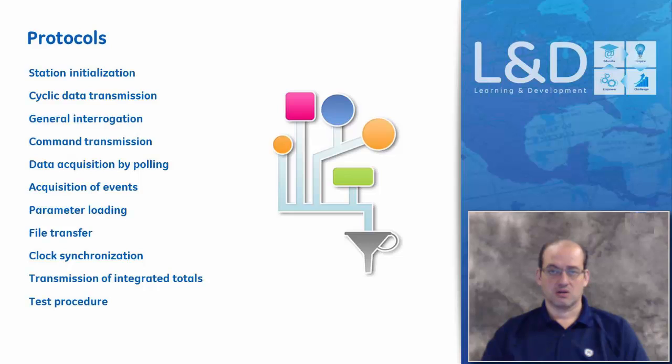So you might want to have clock synchronization supported by the protocol, transmission of integrated totals, and of course support for test situations and test procedures, and support for any installation in the substation, where if there is an installation taking place, you want to put the substation in test or in no-monitor mode, basically.